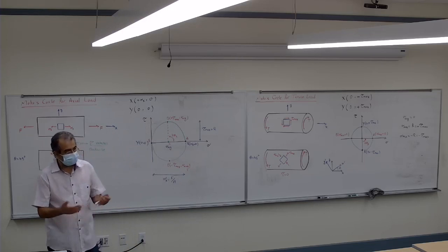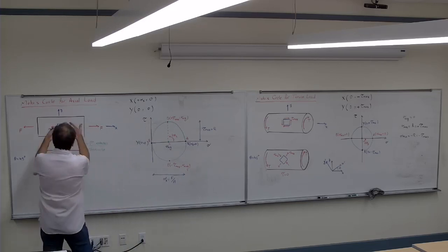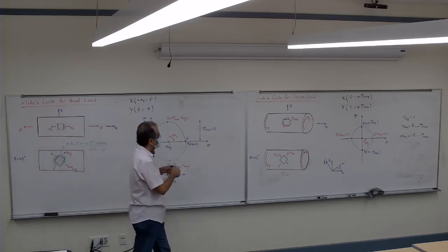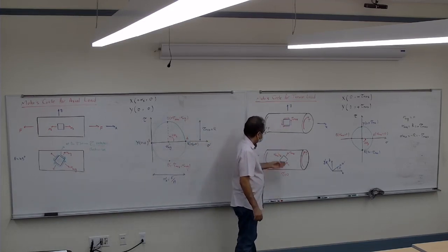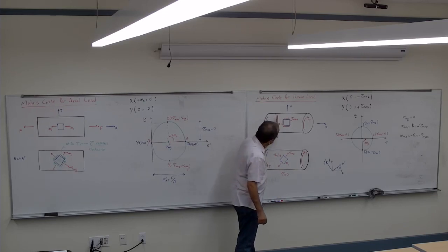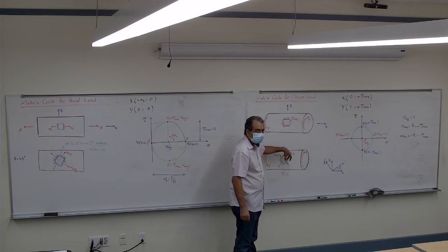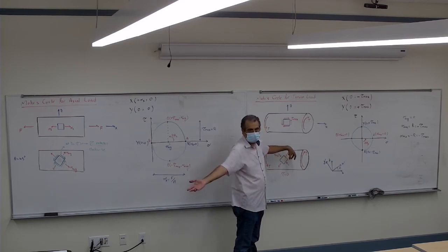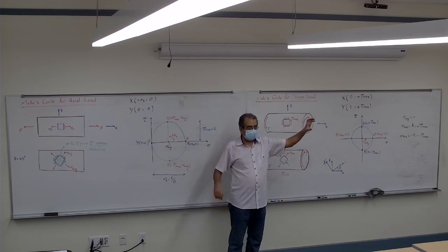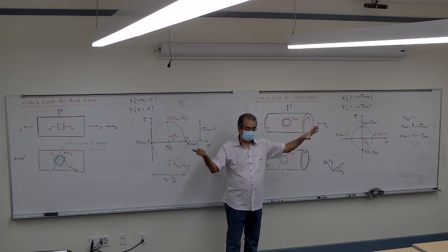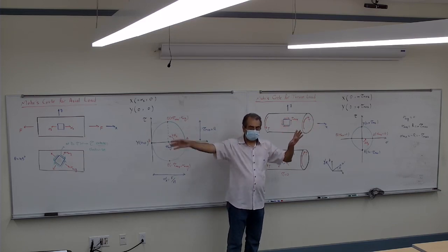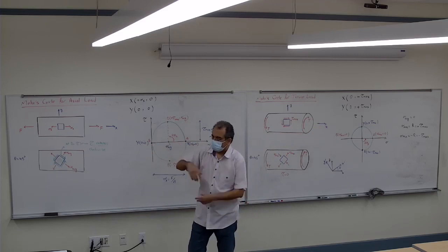What if originally we have only the normal stress or only the shear stress? Again, you see that if you have the maximum shear stress at whatever angle, if I rotate 45 degrees, I get the maximum normal stress. So wherever one of them is maximum, 45 degrees apart the other one becomes max. If the normal stress is max, 45 degrees apart is shear max, or vice versa.